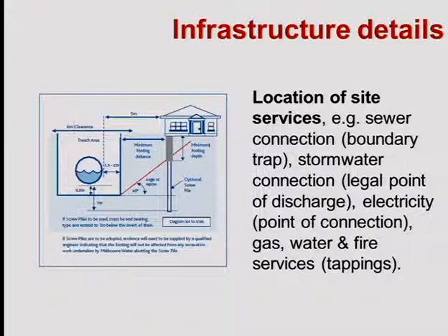So in this case, if there's a pipe there, you can see we've got to bring that 45-degree angle below the lowest level of that pipe, which means you can't do a standard footing system here. You've got to do a footing system which will bring that load and transfer it down. So in this case, the proposal here is to use a series of piles to transfer that load so that that 45-degree angle is further out.